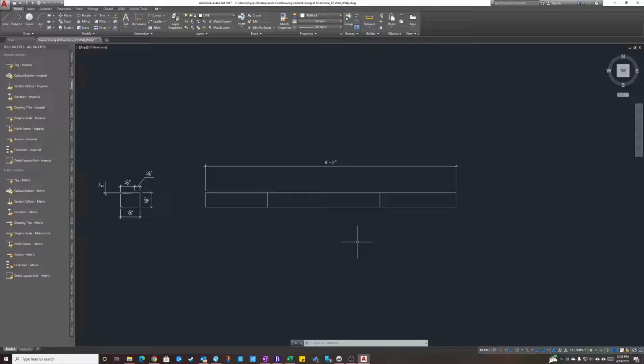Well, first of all, 3/8 of an inch, you're going to have 2 joints. So you take 3/8 of an inch and you times that by 2. That measurement is 3/4 of an inch. So there's 3/4 of an inch of too much space or too much material on the stone right now.